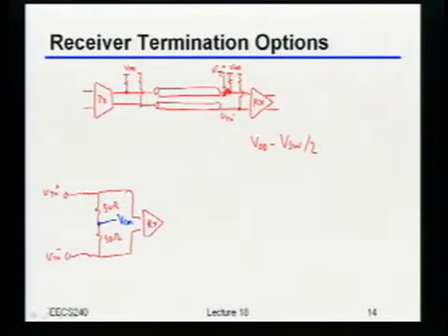Would that set the common mode at the input of the receiver exactly to ground? So I see one person at least shaking their head. Why not? Well, there's a voltage divider. There's 2 resistors. Yeah, exactly, right? On the transmit side, I've got these 2 pull-up resistors, right? So these 2 pull-up resistors would just have a voltage divider with those 2 pull-down resistors.